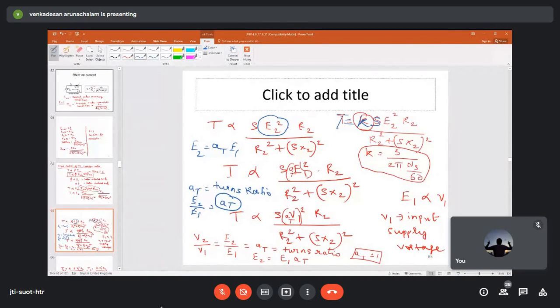And the secondary side of the transformer is static there, but here the secondary side of the induction motor is rotating. That is the only difference. So the induction motor, since it is working based on the transformer working principle, I can call induction motor as rotating transformer.